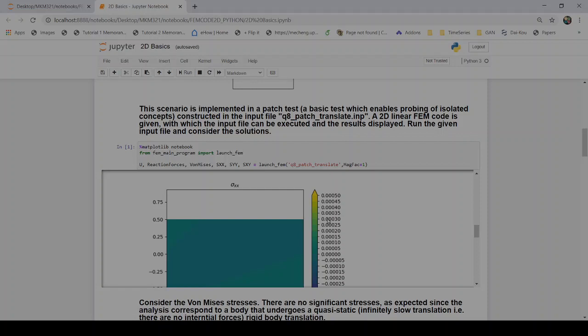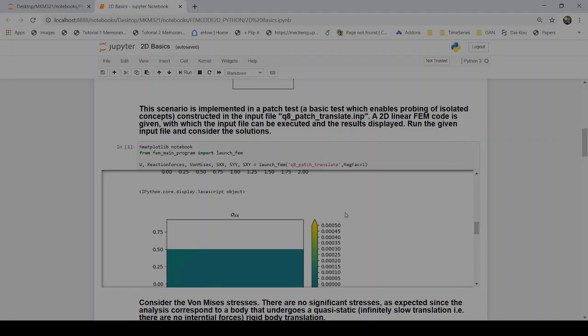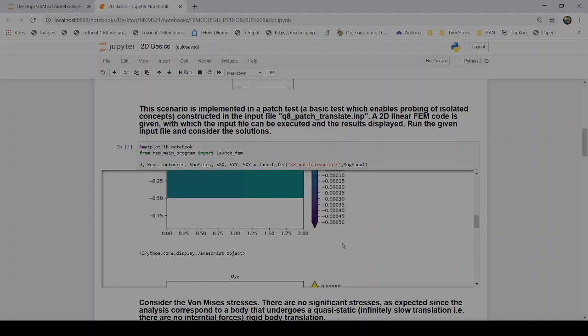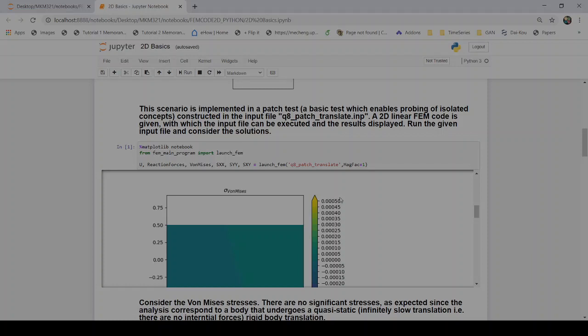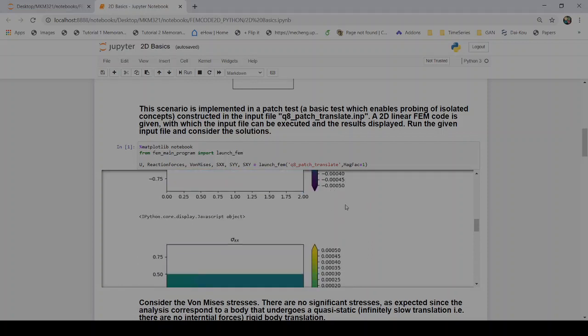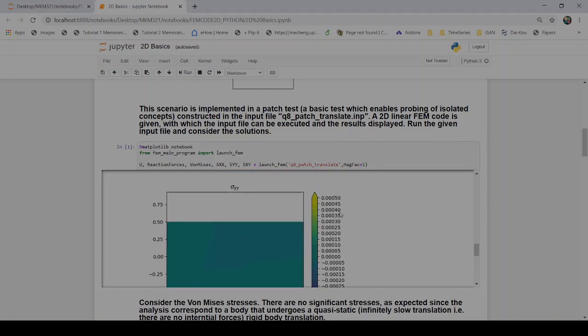When I look at the sigma xx, that's also numerically zero, because remember, we're working with gigapascal kind of Young's modulus and stuff like that. So 10 to the power of 9 kind of order of magnitude, or actually 10 to the power of 11 magnitude. So then 0.0015 is essentially 0. Okay, so that's just important to understand that you interpret this numerically. So it's about the range of the numbers. What's the largest number that you're working with? If that is 2 times 10 to the 11, then anything less than, let's say, 0.01 is going to be 0 numerically. Okay, just to give you a gut feeling more or less. Because typically we have about 12, 13, 14 digits depending on what kind of precision happens inside this. So, but this is numerically 0. Sigma xx, sigma xy, sigma yy also numerically 0.